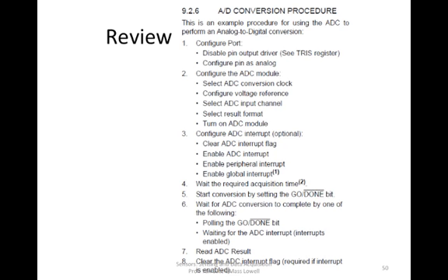By that, we mean you need to set proper values of the ADC control register, or maybe registers, depending on what function you use from the ADC. This includes selecting the ADC conversion clock, configuring the voltage reference, either VDD or external reference, selecting the proper ADC channel, and selecting the result format, left adjust or right adjust. And you need to turn on the ADC module.